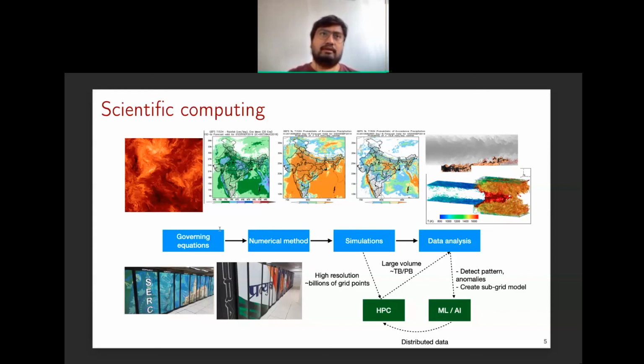Okay. So let me answer this question in two points. The first point is, if you see machine learning applied to fluid mechanics, most of this has been in the context of modeling, right? So in terms of developing turbulence models, and this is where the physics informed networks would come into place, where you want to train the model for either the coefficients in the stress equations or the subgrid stress values itself, with the physics component being the generalizability of the relations, or the constraints such as conservation of mass and momentum being applied as loss functions and so on.